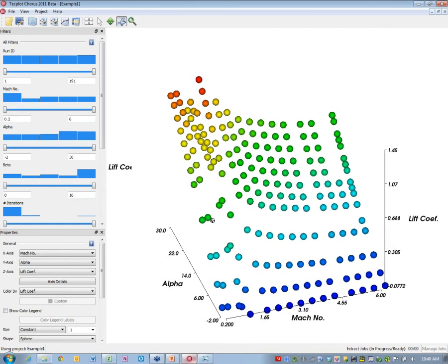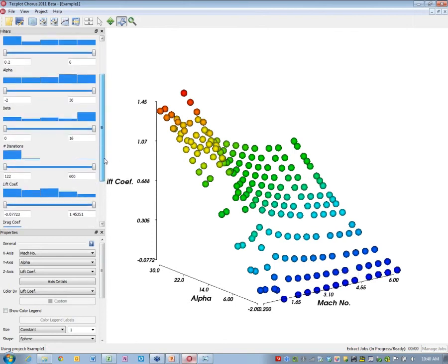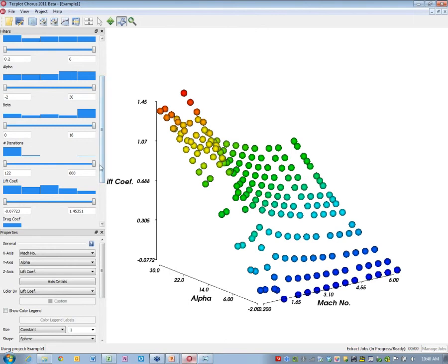Now, one thing when you're trying to put together a surrogate model and come out with a surface that we're actually going to show you, you can go from the surrogate model to a data table that you can provide to stability and control. One thing that you want to do, though, is base it on the best possible data. So you can see that if I look at this histogram, most of the results converged in 150 iterations, but you can also see there's some anomalies here.